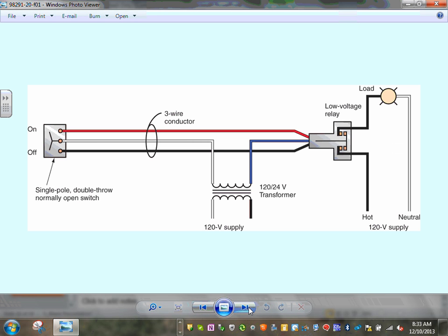Any comments, any questions? I cannot emphasize, when you have a lighting control system, you have to start with a low voltage transformer, you have low voltage switches or occupant sensor, and you have a relay that connects the high voltage to the low voltage, either electronic relay, solid state relays, or electromagnetic relays. So instead of having low voltage switches, I can have an occupant sensor here that does the same thing. Turn this on and off if somebody's walking in the area.